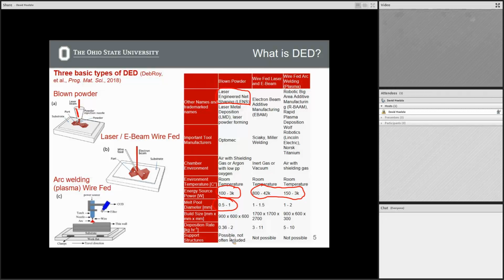So if you're already going to put this in a CNC and machine a finished surface, why go through the extra intricacy of making sacrificial support material when you're just going to machine it away anyhow? So for the most part, support structures really aren't used. You're just building a larger structure than necessary and then machining away what you don't need.